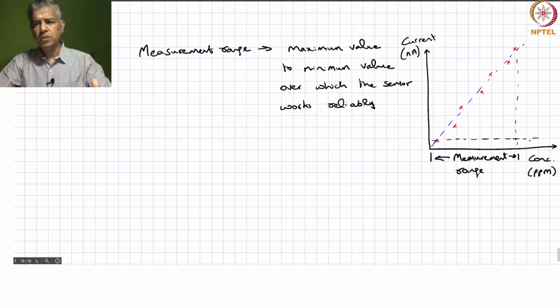So you would say that when you're measuring the current, when you're looking at the display, even without any ammonia present in the environment, you might have the display actually vary in the last few digits, the last few bits of your ADC maybe. So the least significant digits, maybe there's some variation. So that actually puts a cap on this measurement.